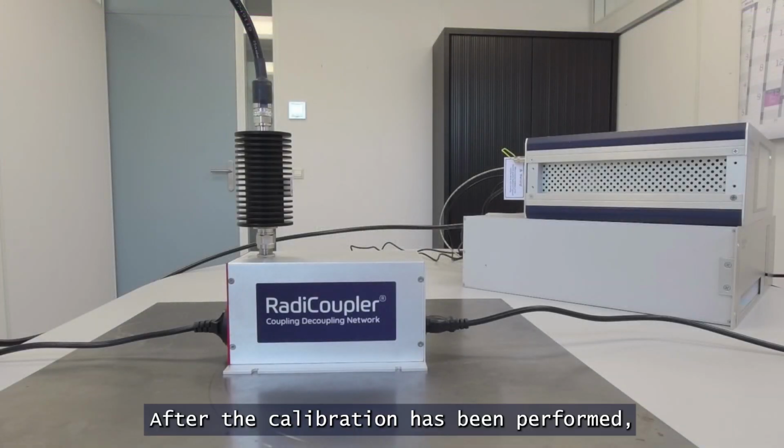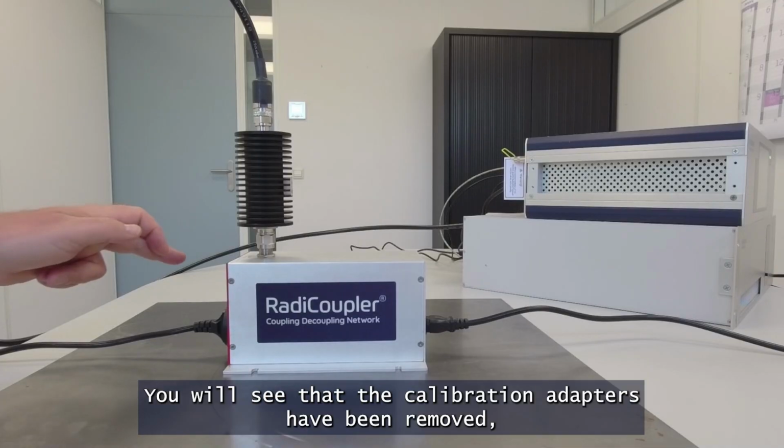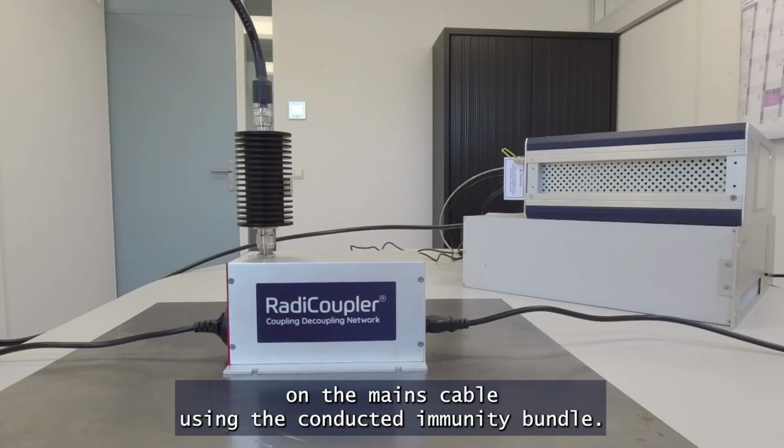After the calibration has been performed, we can modify the setup by connecting an EUT to the CDN. You will see that the calibration adapters have been removed, and a mains cable has been connected to the CDN. This means that you can now perform a conducted immunity test on the mains cable using the conducted immunity bundle.